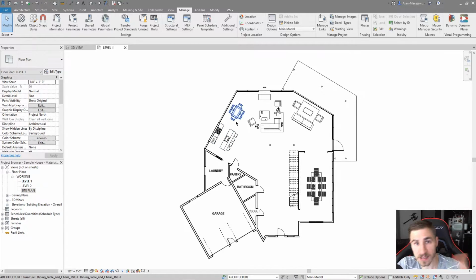Design options really are just copies. In this case, we probably want to use the same elements, but maybe we have completely different models that we want to use for furniture in option B. Well, then we just put those new elements into option B. Easy enough. But if we want to use the same elements and then change the layout, like we're going to do here, what do we do then? Well, we can replace all of them, or we can do something else.